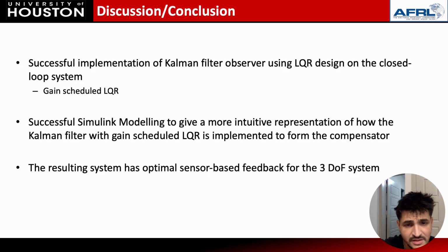So for the discussion and conclusion, we're showing the successful implementation of a Kalman filter observer with an LQR designed in a closed loop system, where the LQR is being gain scheduled in order to create the LQG compensator system, where again the LQR is being solved in one fashion and the LQE is being solved in a different fashion, utilizing the separation principle.